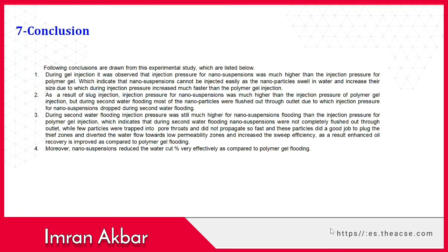So the conclusion of our experiment was, number one, during gel injection, it was observed that the injection pressure for nanosuspensions was much higher than the injection pressure for polymer gel, which indicates that nanosuspensions cannot be injected easily, as the nanoparticles swell in water and increase their size, due to which injection pressure increased much faster than in the polymer gel injection.